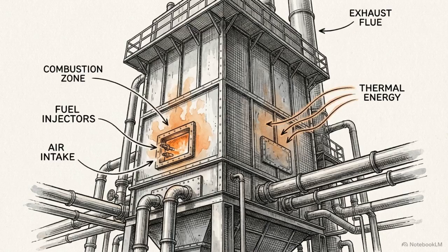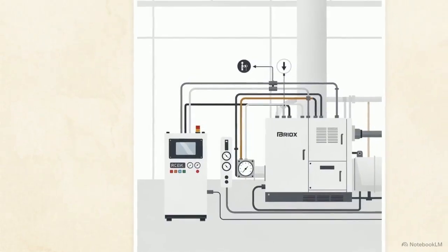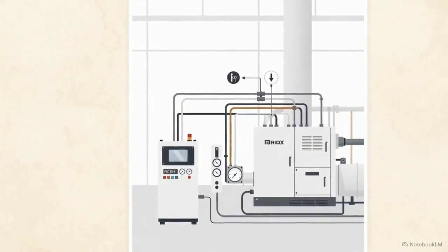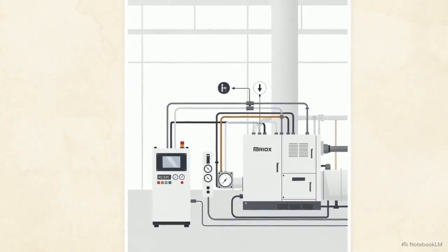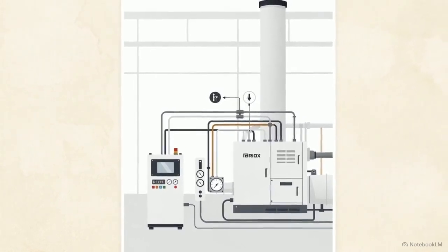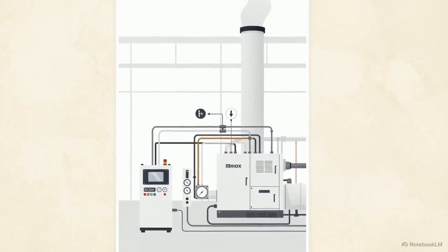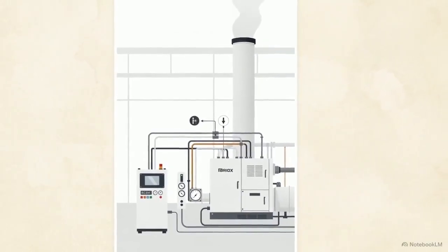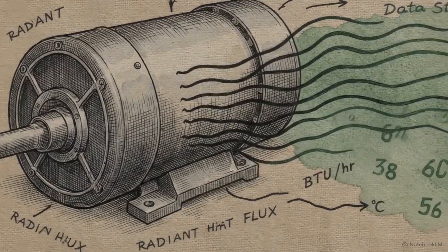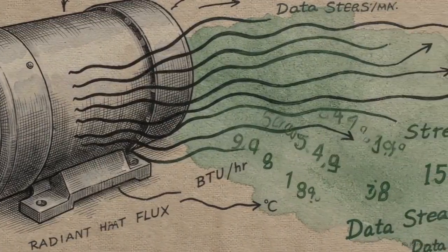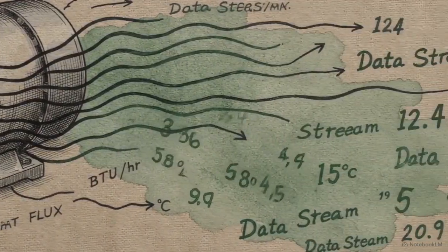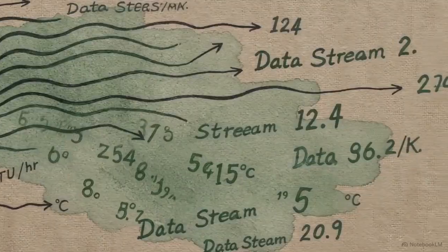We then trace the thermal energy back to its generation source, the combustion boiler. This schematic illustrates the deployment of a flue gas analyzer. By probing the stack to measure oxygen and carbon monoxide levels, engineers can perfectly optimize the burner's air-to-fuel ratio, immediately reducing flue gas losses. By making the invisible physics of heat and gas visible, these tools turn unknown, untracked waste into precise, actionable data points.